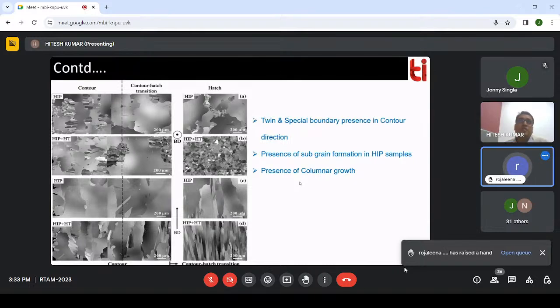Is it possible to calculate percentage porosity with an image analyzer? Yes, on the surface it is possible. The other way is the Archimedes principle, which you can use if there is enough porosity. Or nowadays we have X-ray tomography, which is the best way to calculate the porosities or any defects in your material.